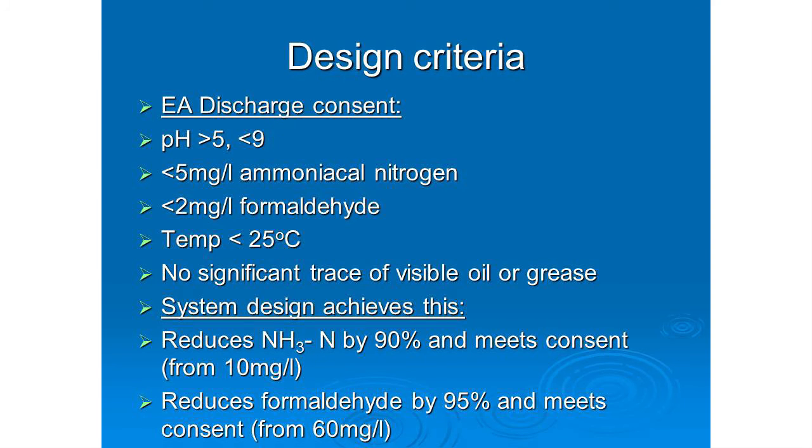One of the most difficult sites we've worked on because we had a discharge consent on this site that we had to work to and design to. So crucially, we had to make sure that there was less than 2 milligrams per litre formaldehyde coming out of that, which the system design achieves. And it's monitored on a regular basis because it's got a discharge consent. And the last time I spoke to the people up on the site, they've not had any issues with meeting the compliance. We've actually had consultants who are working for the same client on other sites ringing us up to ask us how we did this. So it obviously is an effective system.